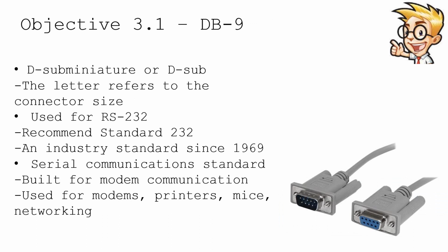If you spent a lot of time with network infrastructure or you've been in a data center, you might be familiar with this type of connection. This DB9 stands for D-subminiature connector, and the size of the connector is B size that supports 9 pins. These are commonly used to send RS-232 signals from your device, commonly to a serial port on the other device. This was originally used for modems and other serial devices. But if you're working in a data center these days, it's going to be common to see these on switches, routers, firewalls, and other network infrastructure devices.